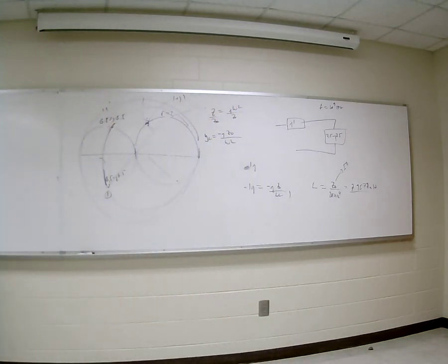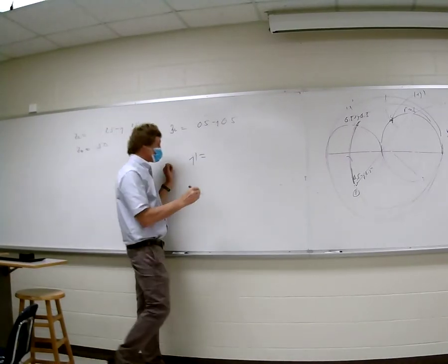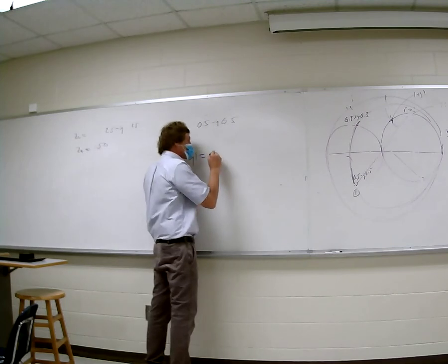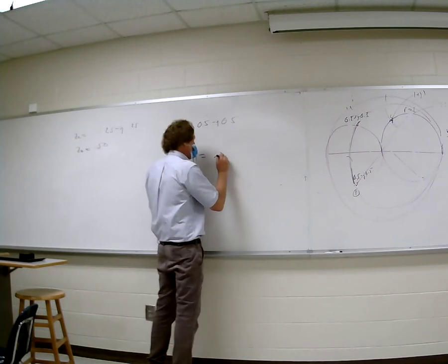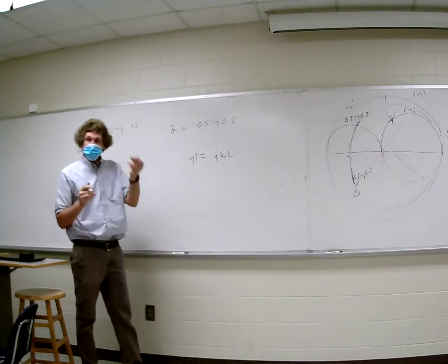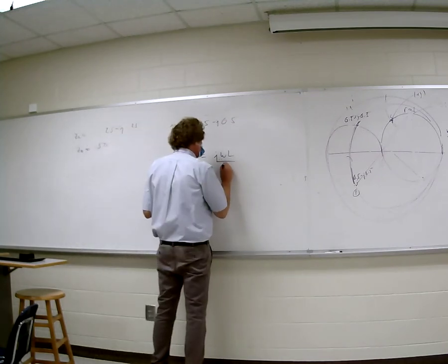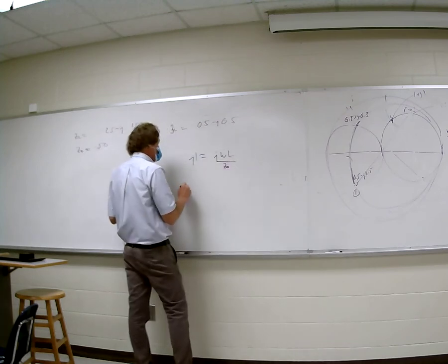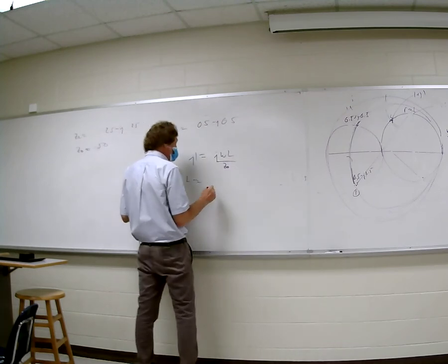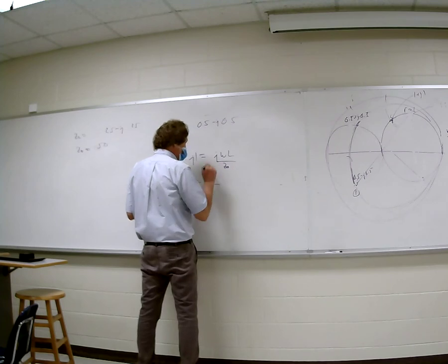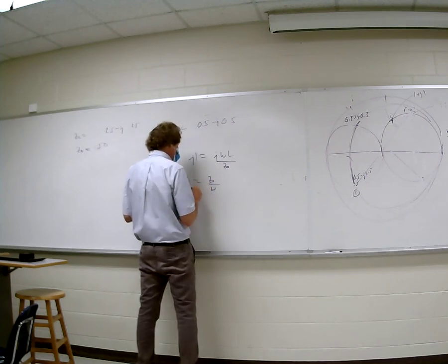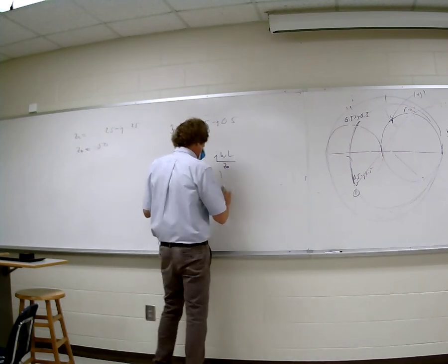So I would say that the impedance J1, which is normalized, you all follow me while I'm doing it, is equal to, well, it's a plus J, it's an inductor. So the impedance of an inductor is J omega L, right? To normalize, we divide by Z naught, correct? Now that means we could find the value of the inductance equal to Z naught divided by omega. And what do you get for that value, by the way?